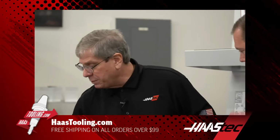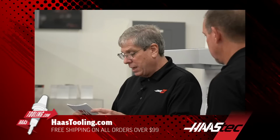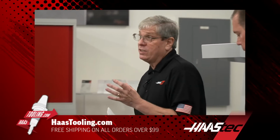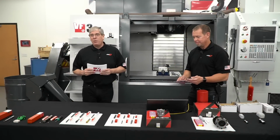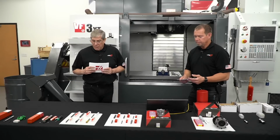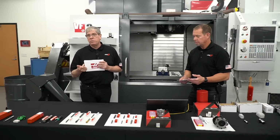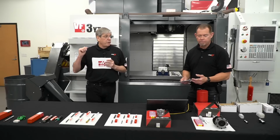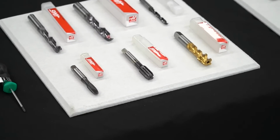If we move up to the taps now, we have a variety of different taps. The tap sizes are available in 16 different inch size ranges, and metric is coming soon, folks. We get that question all the time. We carry them in sizes from 4-40 up to 5/8-11. We've also got them in 5 different coatings. There's a bright coating, generally used on aluminum and non-ferrous materials. There's a hard slick coating. There's a titanium aluminum nitride, and titanium carbon nitride.